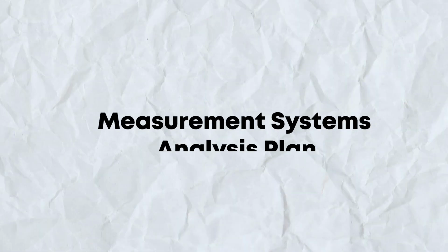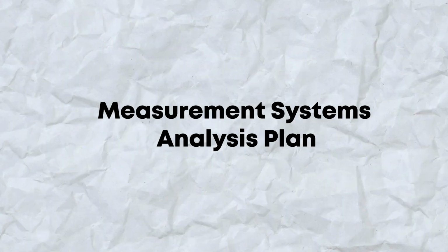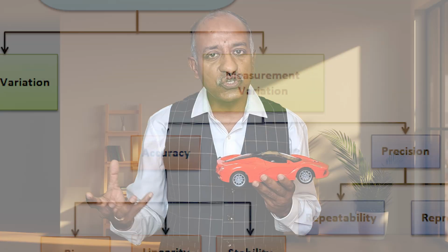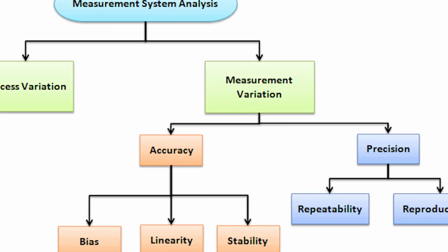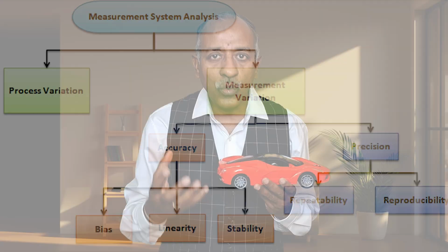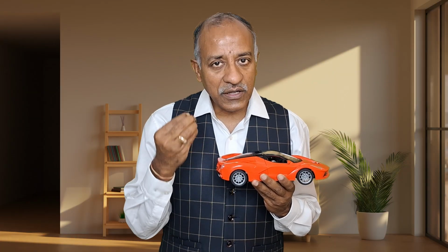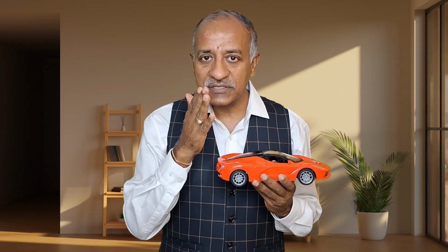Then another important thing here is output number 8, which is talking with respect to the MSA study, which is the 4th edition of AIAG. In the control plan, there are so many measuring systems. It can be visual, it can be dimensional. There are different measuring instruments which are being used. So how reliable are they? How much is the competence of the people who are doing it? Can we trust the repeatability and the reproducibility? Because if we can trust, there is a possibility that whatever output is coming, it will meet the quality level. So MSA is a very important indicator with respect to that.